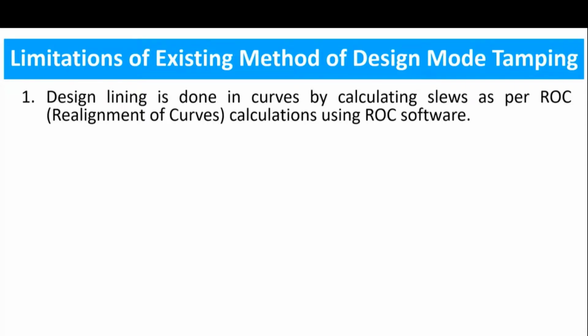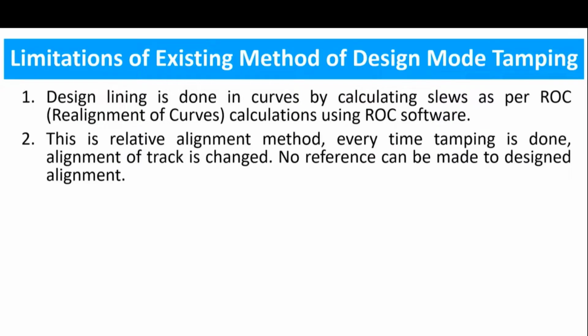Then what are the limitations of the existing method? Again, it is a relative method and realignment of curve calculations are to be done. Then every time the tamping is done, the new alignment is created without any reference to the previous alignment. So every time new references are created.